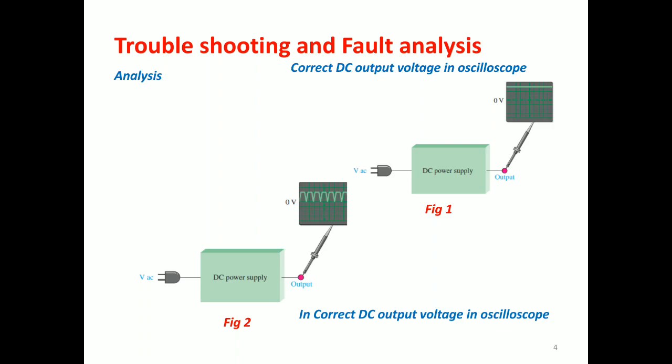However, in the case of power present but the output voltage is wrong, beyond the power check, use your common sense to detect obvious defects such as a burned resistor, a broken wire, a loose connection, or an open fuse. Since some failures are temperature dependent, and 90% of electronic products are temperature dependent, you can sometimes find an overheated component by touching the electronic items.